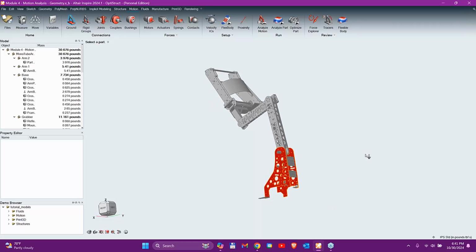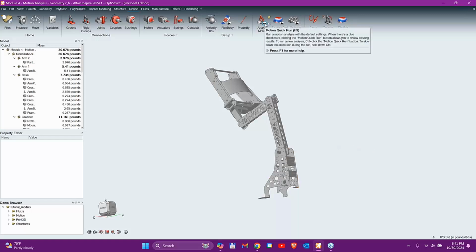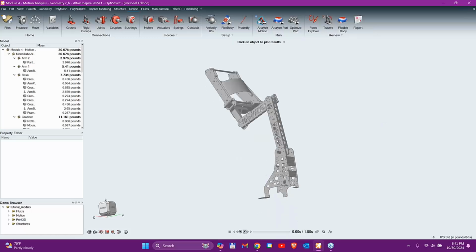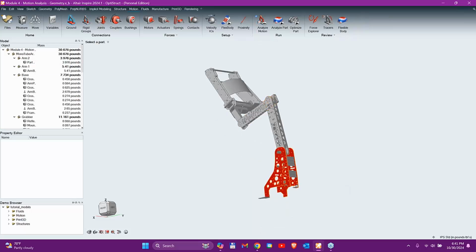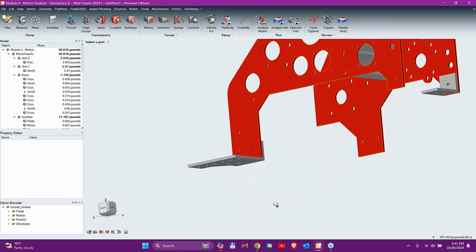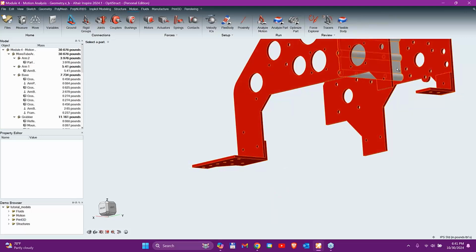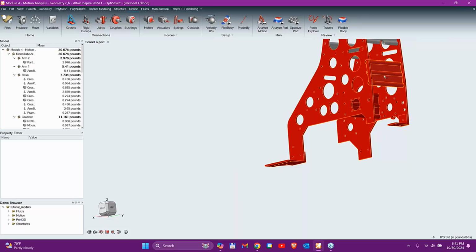And what I typically do in this case is I do a step and I do a quick analysis to see if that worked the way I wanted. So I click Analyze again, and you can see it worked, but I seem to have missed a few pieces here. You can see these little support members here. And the attachment members are falling as well. So I can just come back to my ground and maybe zoom in here. And had I zoomed in, I would have seen them here. So they're still staying in gray. So I'll pick all these.